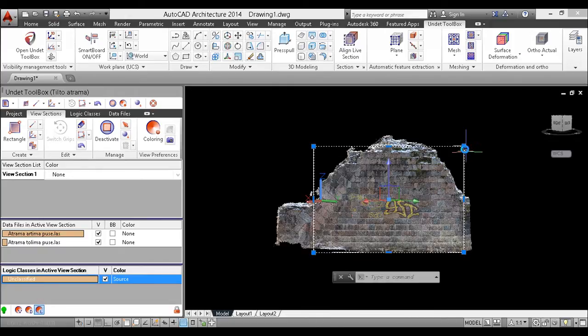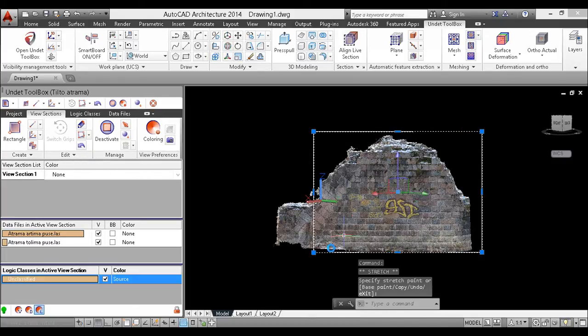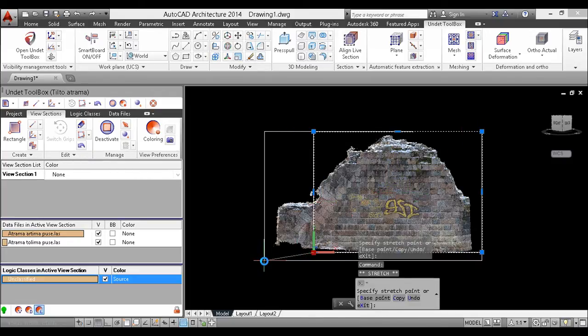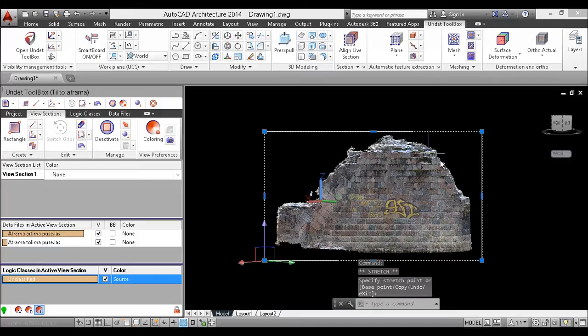And here is my polygon. I will increase it to mesh the entire structure, but you have to be aware that this mesh works, let's say, up to 90 degrees. So it means that if the surface is turning more than 90, the mesh is stopping. So it will stop automatically where it reached close to 90 degrees. I'll press enter now. Again, a couple seconds for mesh calculations.